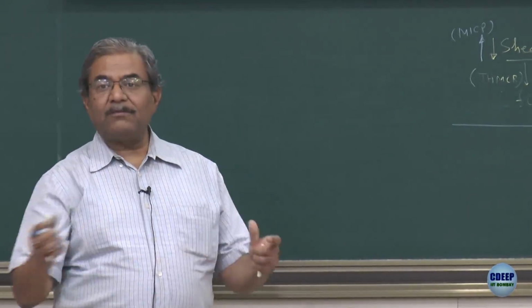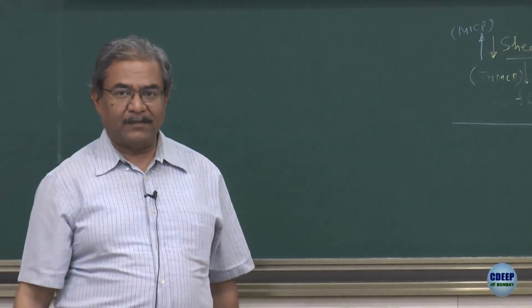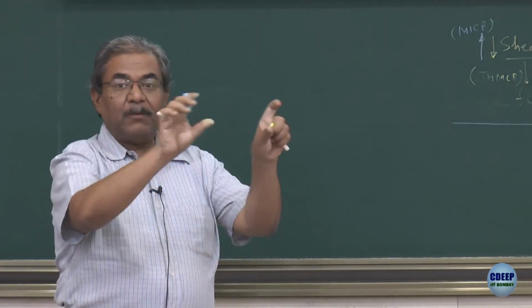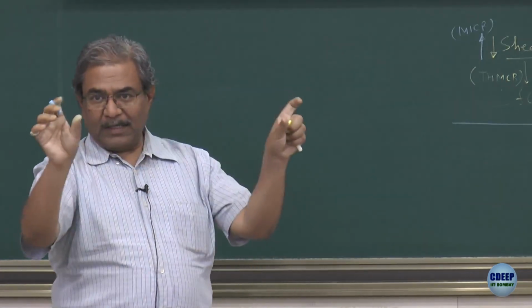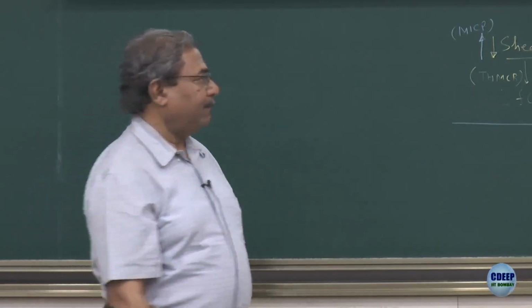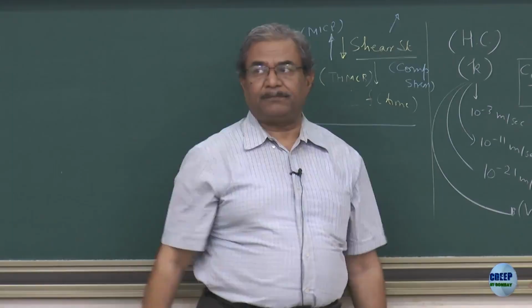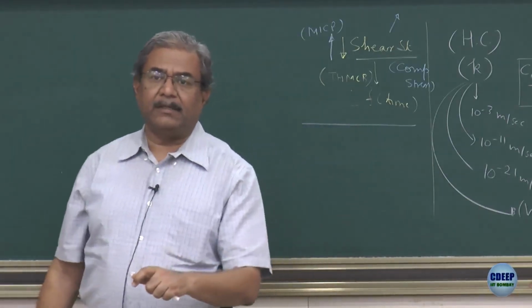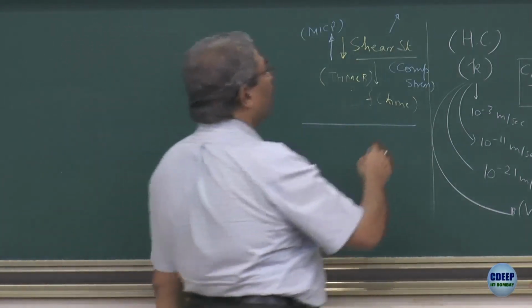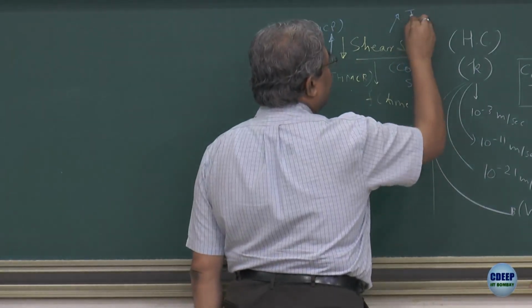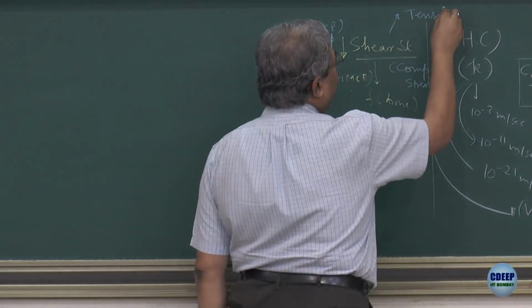In most of the systems where, let us say, tunneling is being done, the material should be able to take tension on the crown portion, all right. Even if it deflects, it should not fail, it should not collapse. That is another application. So, this is where we actually talk about the tensile strength of the material.